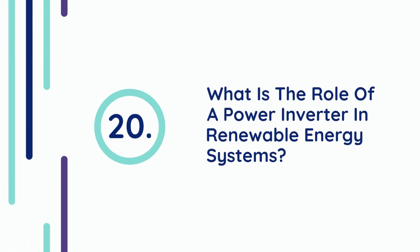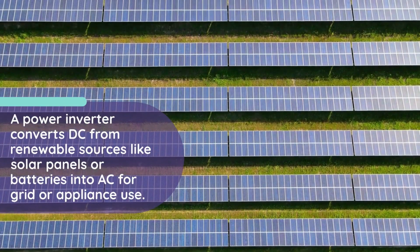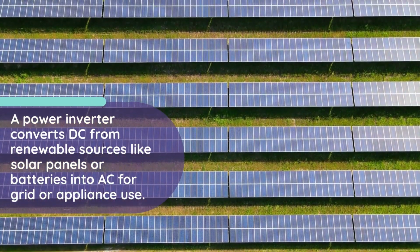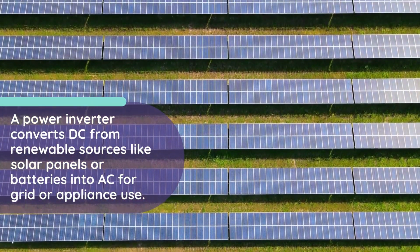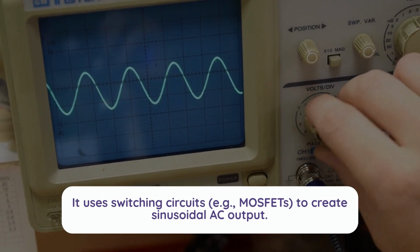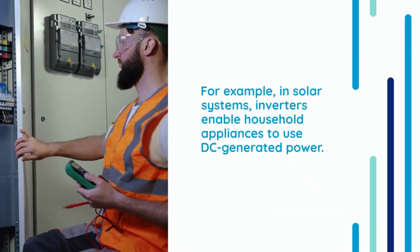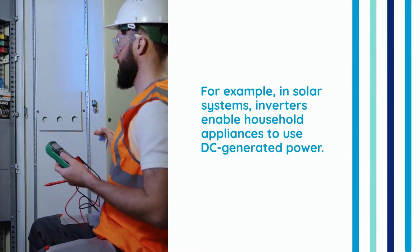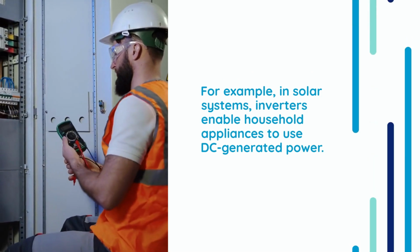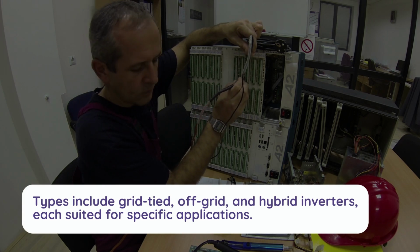20. What is the role of a power inverter in renewable energy systems? A power inverter converts DC from renewable sources like solar panels or batteries into AC for grid or appliance use. It uses switching circuits, e.g., MOSFETs, to create sinusoidal AC output. For example, in solar systems, inverters enable household appliances to use DC-generated power. Types include grid-tied, off-grid, and hybrid inverters, each suited for specific applications.